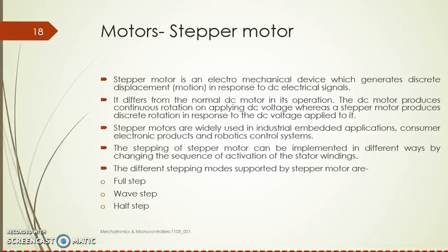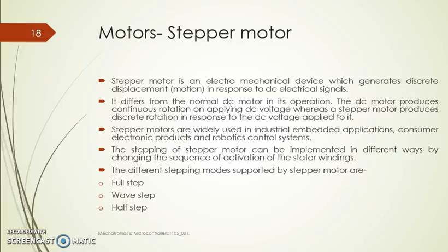Let us learn about how to interface different motors with 8051. Let us study about stepper motor initially. Stepper motor is an electromechanical device which generates discrete displacement in response to the applied DC signals.